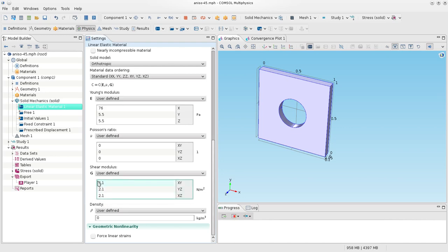So this may not be very realistic. I just borrowed the values. And again, in that example we solved, the Poisson ratios were not zero. There was a Poisson ratio xy and yx. They're not the same. I just assigned everything to be zero. Again, this is not necessarily realistic from a composite materials point of view, but I've just assigned it to be zero so that we can think of the structure of the compliance matrix more easily.